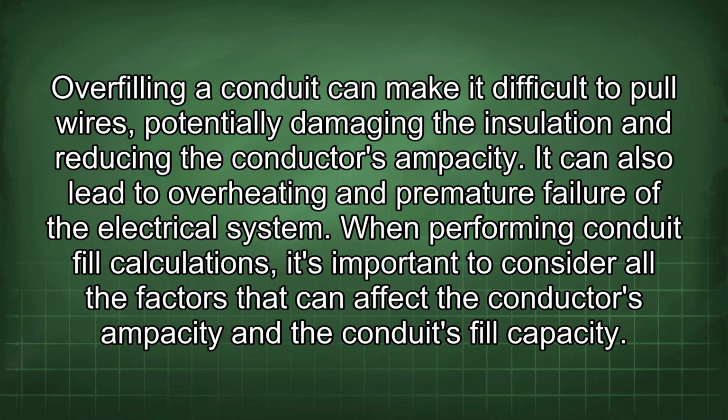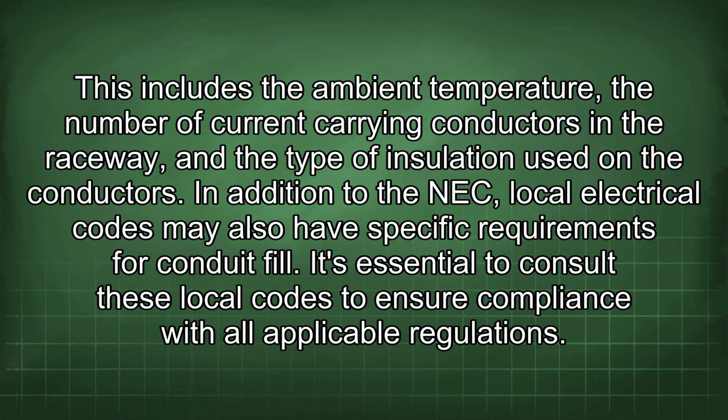When performing conduit fill calculations, it's important to consider all the factors that can affect the conductor's ampacity and the conduit's fill capacity. This includes the ambient temperature, the number of current-carrying conductors in the raceway, and the type of insulation used on the conductors.